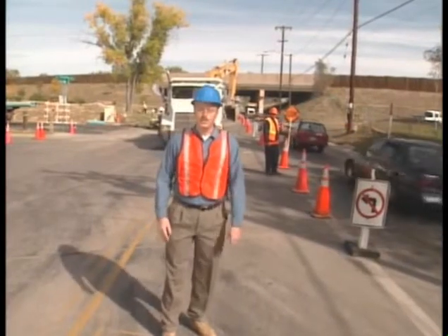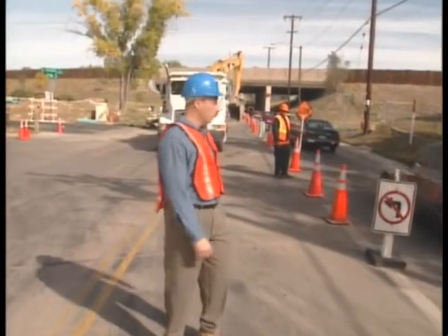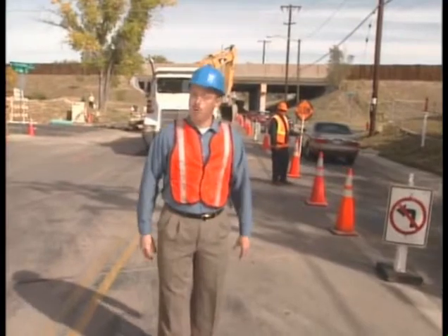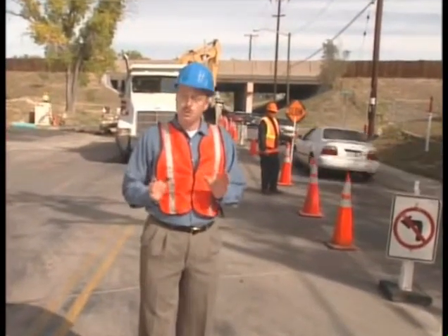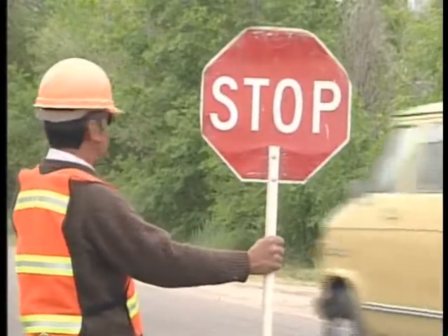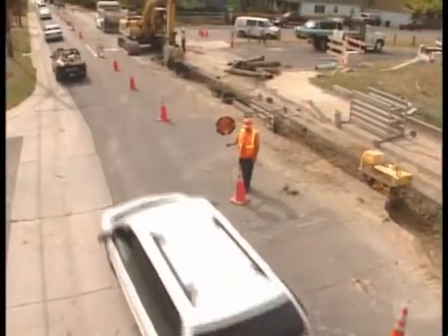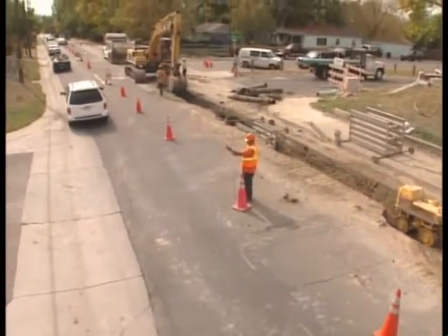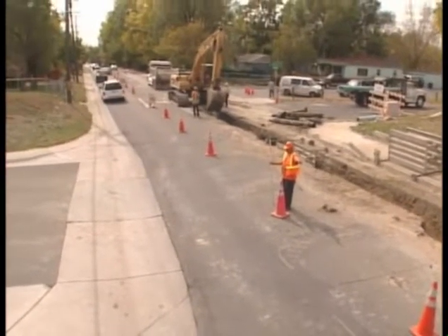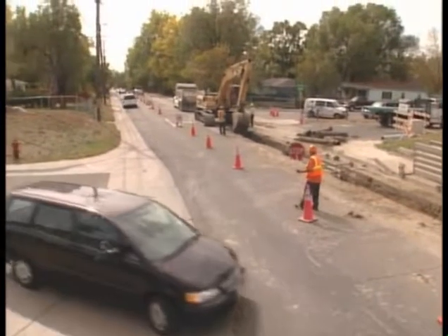Let's take a moment to discuss the role of the flagger in traffic control. Don't underestimate the importance of the flag person. This person is critical to the safety of the entire work crew and to all drivers entering the area. This person should have a thorough understanding of the project and be trained for traffic control. The flagger should be properly outfitted in reflective highway safety clothing, including a hard hat. The flagger should be positioned where drivers can clearly see the person, not partially hidden behind trucks, trees, or signs.